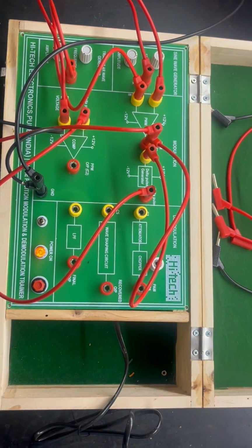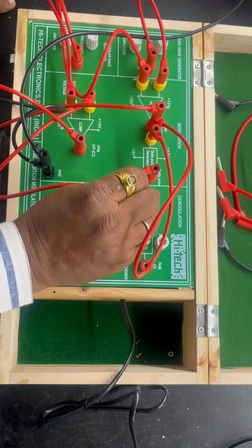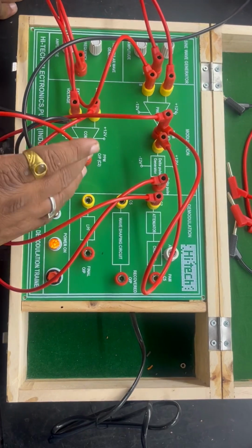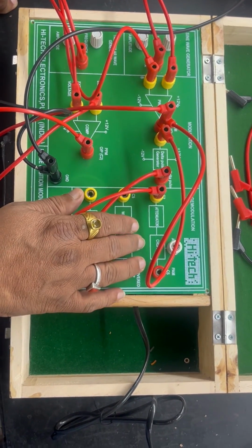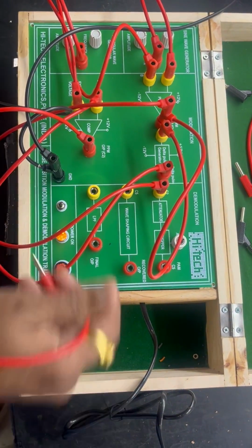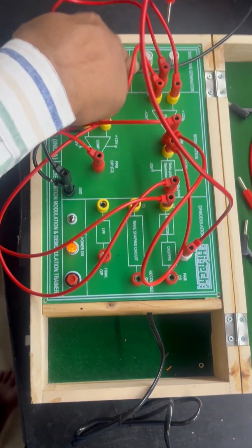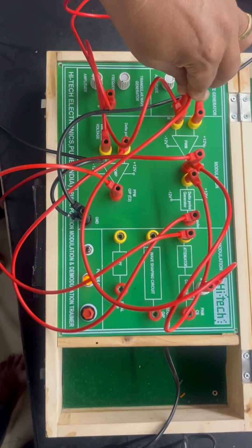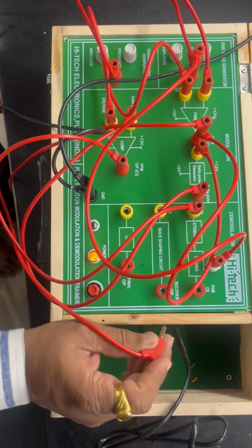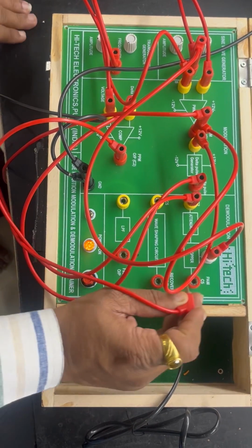Now I am connecting this PPM output C2 to here, marked C2. Here an attenuator is used because the amplitude of this signal is high, so we have to attenuate it to get the proper output. And at the chopper input you have to apply the sine wave, marked A. So I am connecting the sine wave. And now I will be observing PM. This is a step-by-step circuit design and checking for this PPM demodulation circuit.